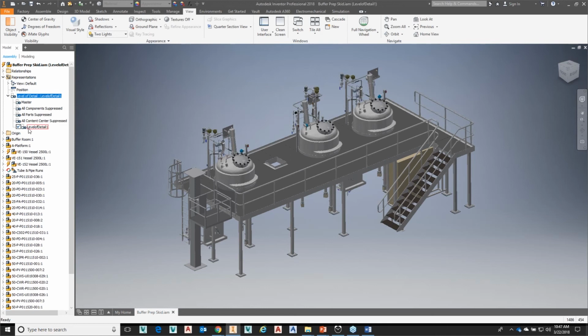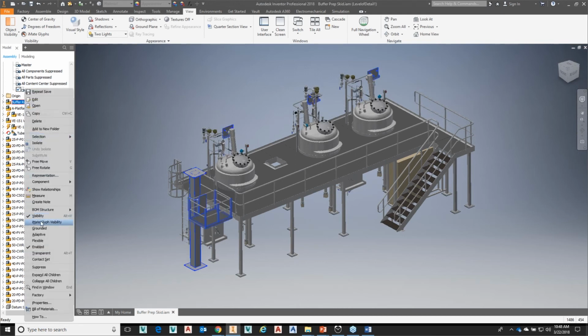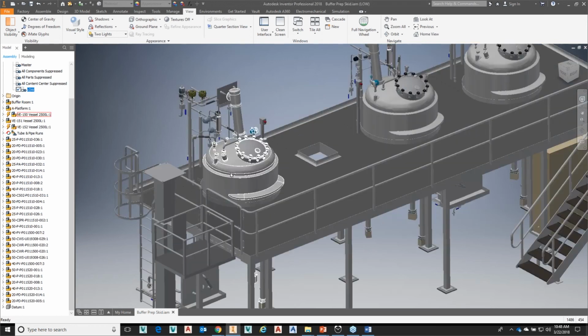Okay, and when I manually create it as opposed to a substitute, I'm basically right-clicking and suppressing and unsuppressing some of these components manually one by one. So little things that maybe I don't need to see on the drawing level or just at a working level, I'll turn off. I'm going to rename this to low. Okay. And right now, this subassembly is loaded at its fully detailed master level of detail representation. We're going to watch the numbers here. We're at 1486 and 454.